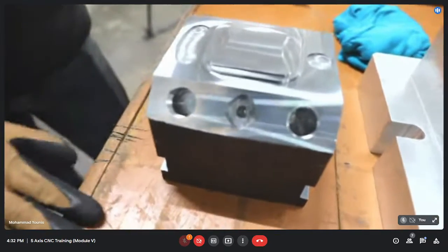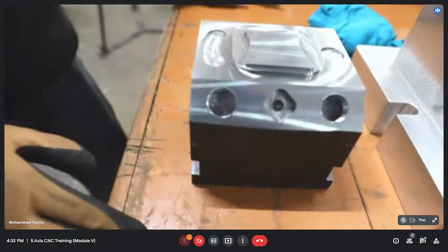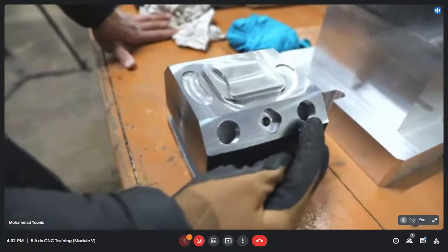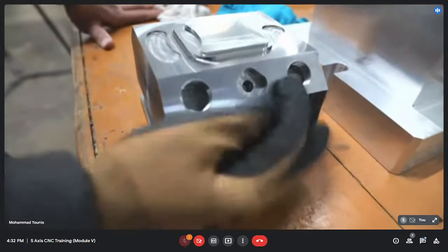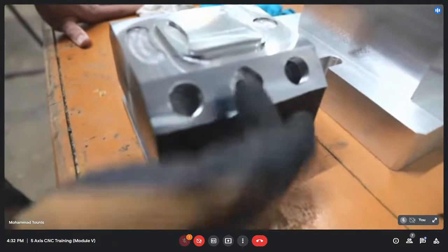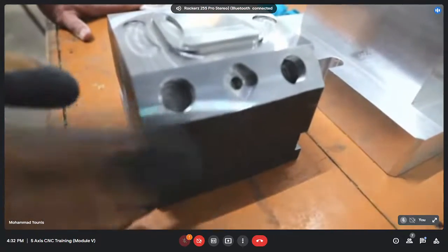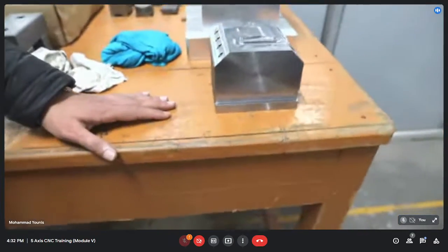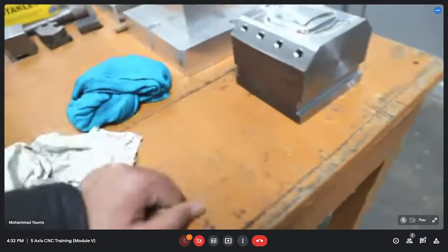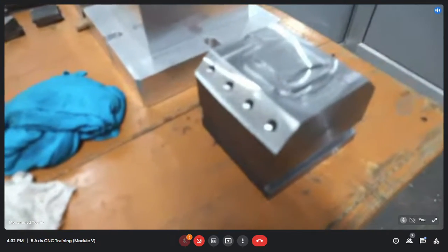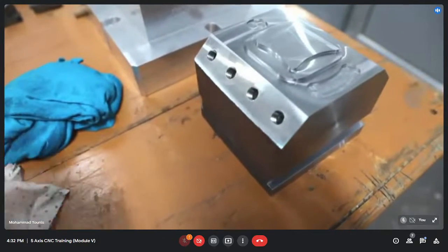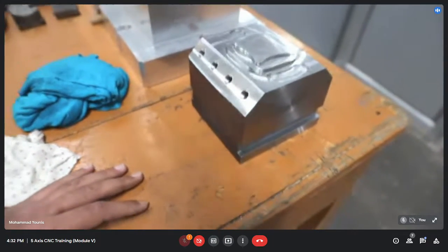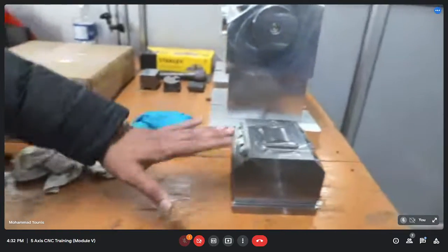Then we have these same programs, same operations that we have performed on our workpiece right now. Like there is a thread milling operation, pocket milling and thread. This is a square pocket, and there is a drilled hole. And similarly, this is also a thread milling operation. And on the other side, we have also performed this tapping operation here. In a similar way, we first drilled here, then enlarged the hole, and performed this tapping. And this all is done at some angle.